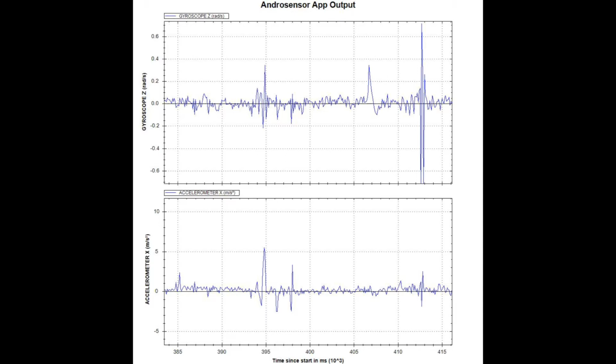So this is a case where it's taking quite a bit of time. It's taken almost 15 seconds to make this move. It's making really rapid changes to the steering wheel, so you're feeling that both in the acceleration as well as taking a long time to move over because it's such a long move. So I'd call this a failure. I'm sure Tesla is aware of this, which drove some of the changes in the later releases. And out at about 412 seconds, you can ignore those big spikes because I was using that just to mark the data.